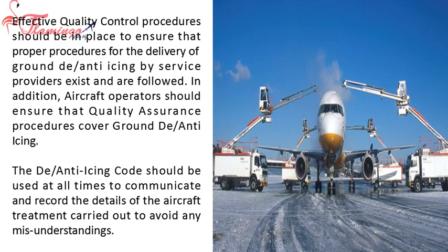Effective quality control procedures should be in place to ensure that proper procedures for the delivery of ground anti-icing by service providers exist and are followed. In addition, aircraft operators should ensure that quality assurance procedures cover ground anti-icing. The anti-icing code should be used at all times to communicate and record the details of the aircraft treatment carried out to avoid any misunderstandings.